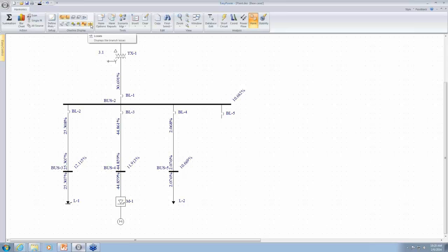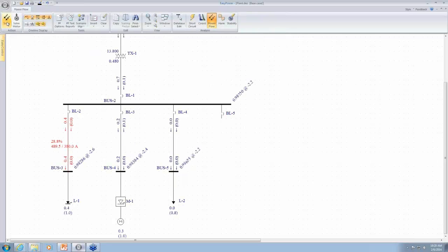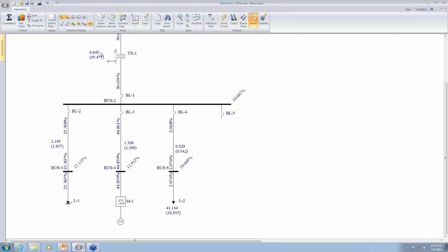Now, we already said there are lots of losses in the system because of harmonics. To calculate all the losses from the different harmonics, you click on this button and you can see how much additional losses there are. Now let's compare that with just the fundamental loss. To look at the fundamental loss, you would have to go to Power Flow, Run Solve, and look at the losses here. See, 4.9 kilowatts is what you would get as the losses, but in Harmonics, you'd get 6.6. So higher losses and more heating, and you can get damage from higher heating.